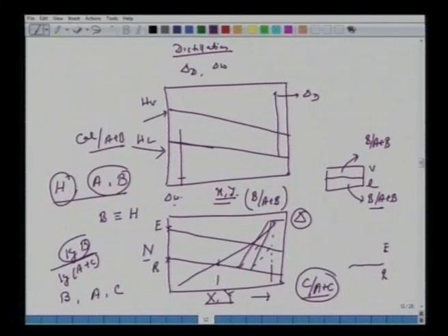But nonetheless, from the qualitative point of view, we can have very similar situations analogous to what we had in the case of a distillation column with an open system, in which case we have one reflux at the top and at the bottom we have this open system, no reflux. So pure steam comes from some other plant or some other unit. So here also we can have a feed in the extraction train of cascades, feed enters somewhere here, and you take out this extract, make it solvent free, put it on a separator, and send back the solvent-free solute, with the streams in opposite directions.